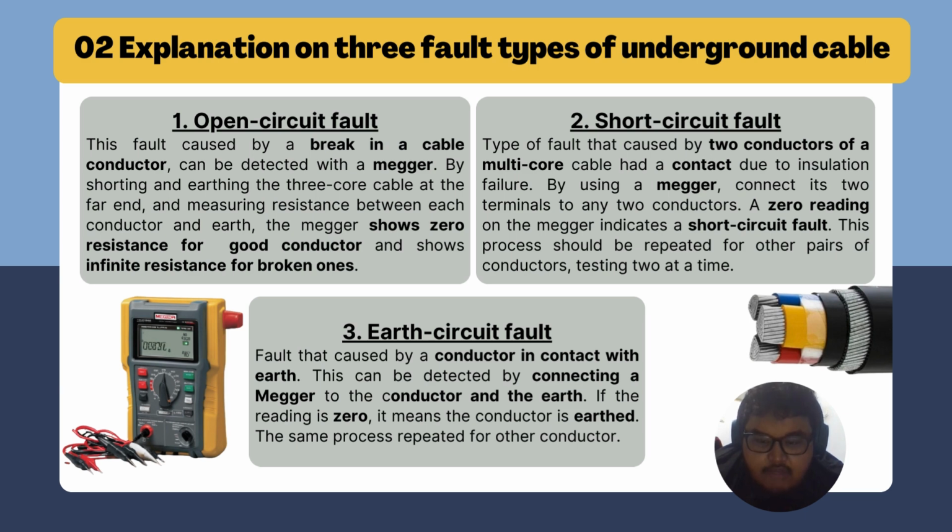Next is the short circuit fault, which is caused by two conductors of a multi-core cable that have contact. Also, by using a megger, we could detect the fault by connecting the two terminals with any two conductors. A zero reading indicates a short circuit fault.